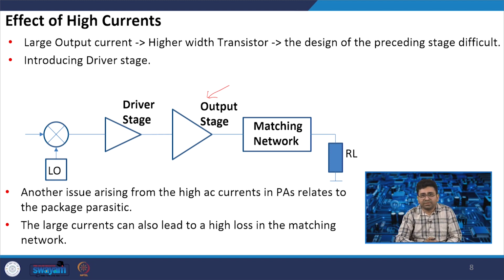The previous stage, if a mixer is directly connected to the output stage or the PA, cannot drive that much high capacitance. So, what you need is to introduce a driver stage in between, so that it can sufficiently drive that much high capacitance.